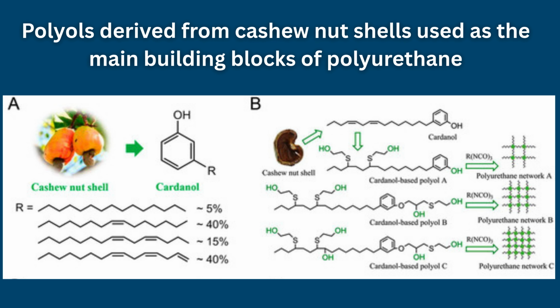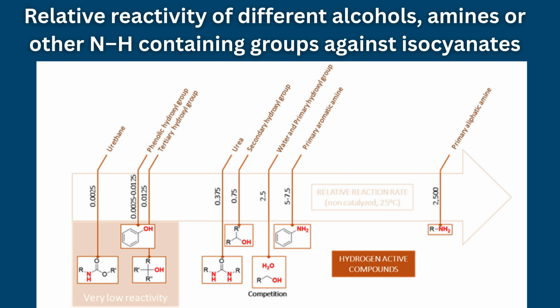In polyurethane foams, CNSL-based polyols have demonstrated improved performance characteristics, including enhanced compressive strength, uniform cell structure, and increased thermal stability. The presence of multiple reactive sites in these polyols facilitates rapid crosslinking, leading to higher crosslink densities and improved mechanical properties. Additionally, the hydrophobic nature of the alkyl chain contributes to moisture resistance, which is beneficial for insulation and